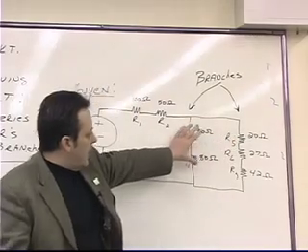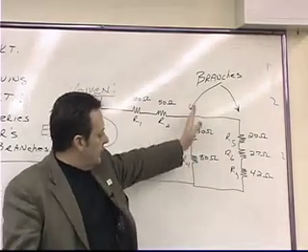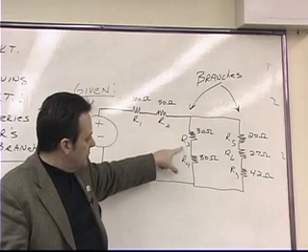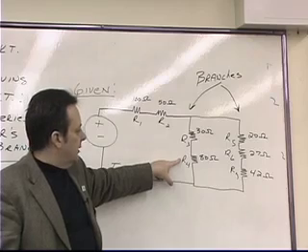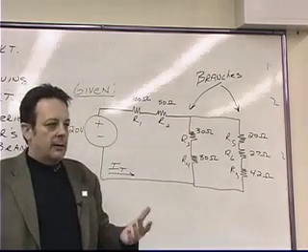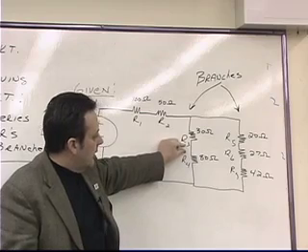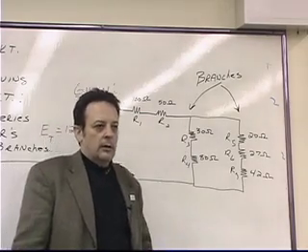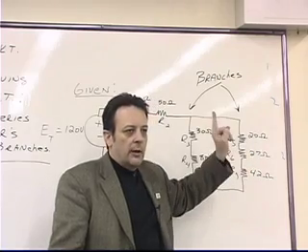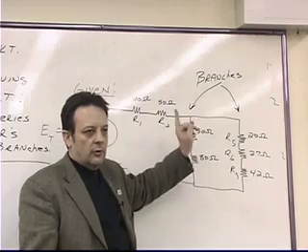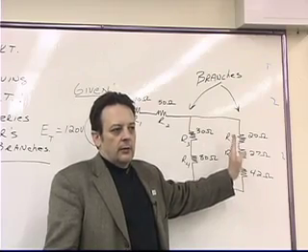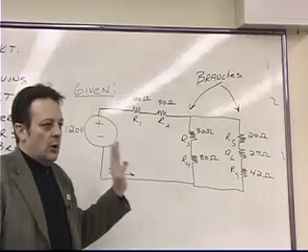Then we look for another branch. And as we move from right to left, we find the second branch. In the second branch, we find two resistors, R3 and R4, and clearly those two resistors are also in series. Okay? And so a 30 ohm and an 80 ohm resistor are in series and could be combined by adding them algebraically and ending up with one resistor, and that would represent the same electrical effect as having the two individual resistors. So basically we've taken these three resistors over here and turned them into one. We've taken these two resistors over here and turned them into one. And so now we just have two resistors in parallel with each other. Okay? If we've done the first step, that's what we've accomplished so far.